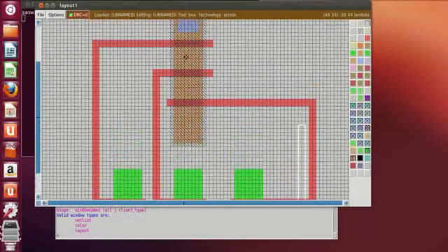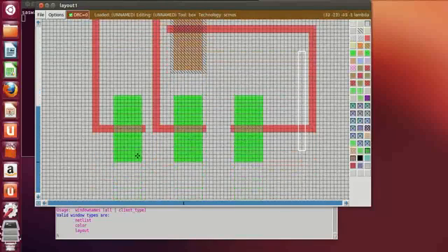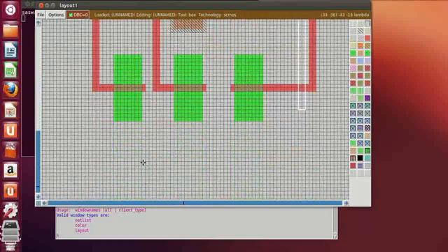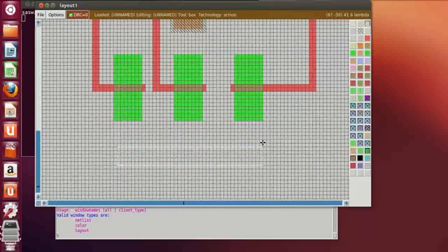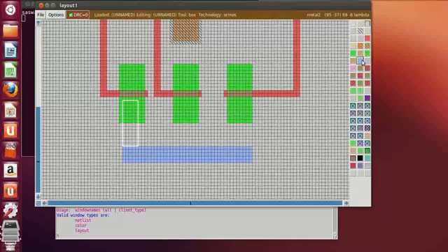Now these are the common portions, that is common source drain, but this is the drain terminal, these three are drain terminals, these three are the source terminals. So the source of the NMOS is always connected to ground. So select the area, middle click on M1, then zoom it and see how much is the width. It's 5. Middle click on M1, middle click on M1, similarly over.